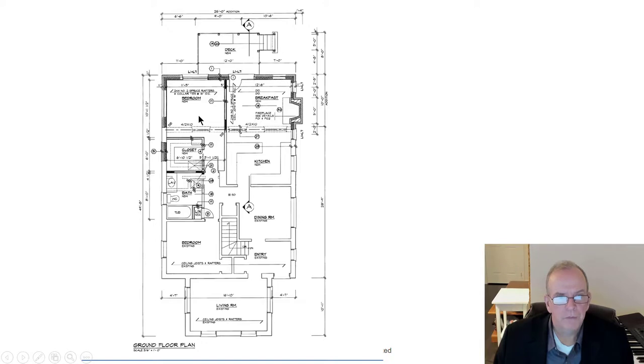Breakfast room, bedroom over here, bedroom over there. This must be the master bedroom given the walk-in closet effect over here. This dashed line over here is telling me there's an attic access hatch. This looks like the old-fashioned solid masonry fireplace going in here. This would be the fireplace details that I showed you back in chapter 13. So that sort of connection is going on there.